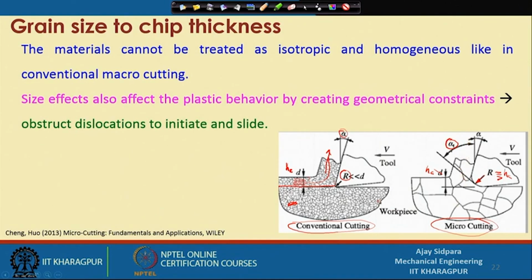Now, if you see the grain size here, you have seen that there are many grains coming out as a chip, but that is not happening here. If you draw one line through this particular line, then this whole grain is going to be cut when this tool approaches it. Other than that, some of the grains are individually oriented and located randomly at different locations, and because of that you have to create a lot of energy here to remove that material or to fracture this particular grain.